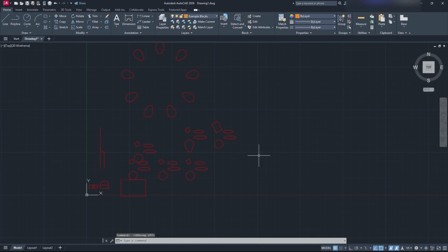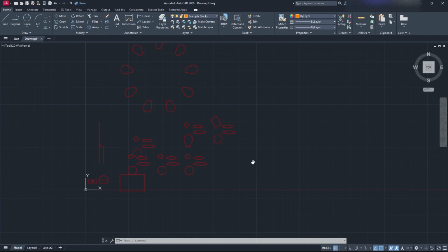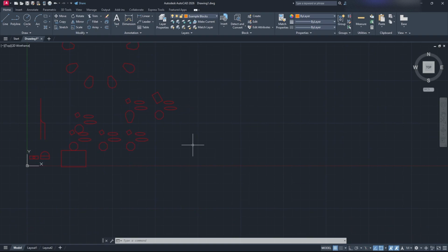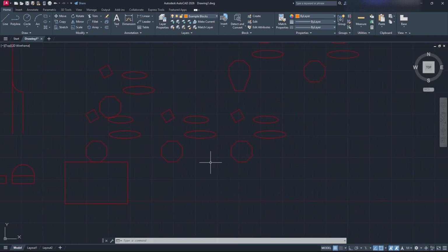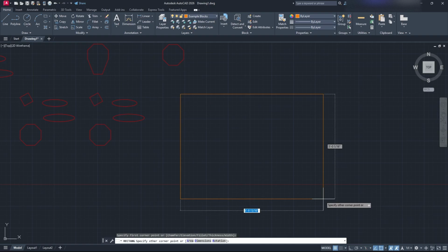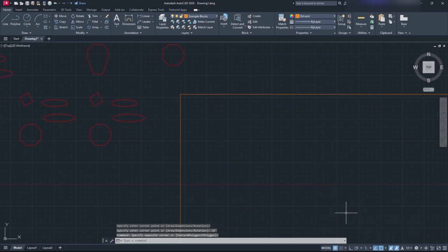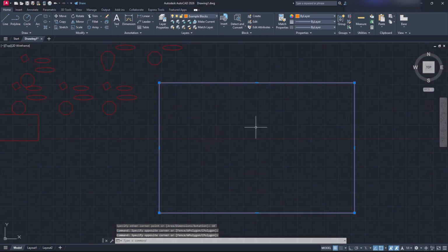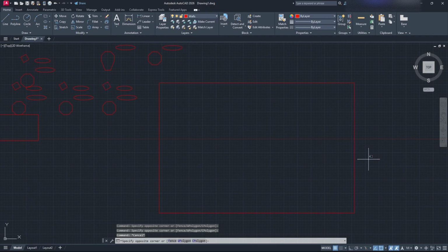Okay, guys, so the next thing that we're going to want to do before we move on is talk about offsetting. Offsetting is really important, especially if you're going into the architecture space, but it's important if you're going into other things as well. So I'm just going to quickly show you what offsetting is. Let's say I want to draw a floor plan, and I just have a square here. Let's say it's a 15 by 10 foot shed. So I'm actually going to switch my layers here. I'm going to go to my walls. I'm going to select walls.